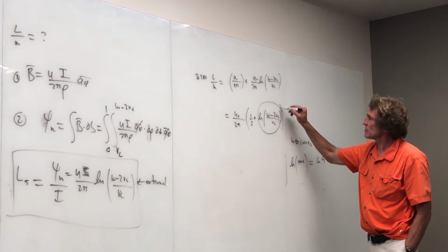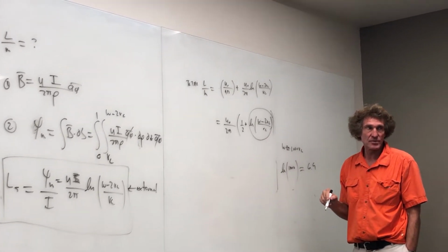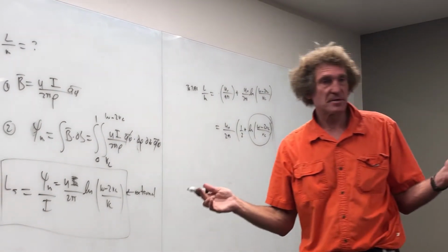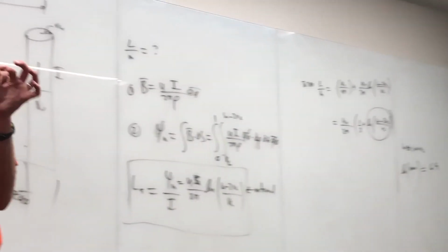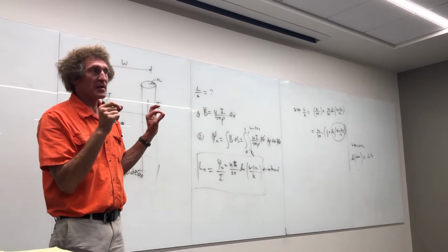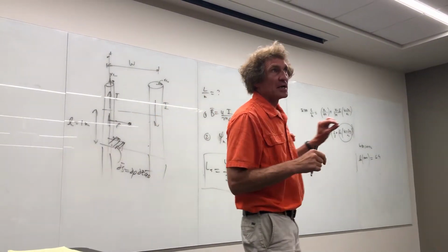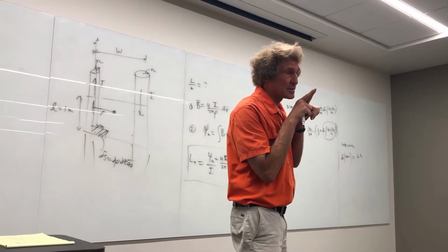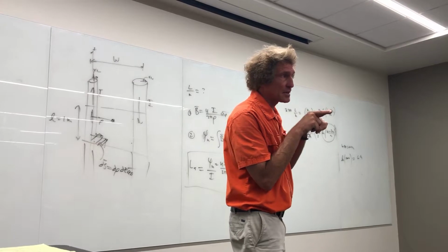My point is this. The actual external inductance is much, much greater than the internal, even for typically power lines that are separated a great distance. But if you're talking about twisted pair circuits, you know what a twisted pair is? You have wires that are twisted with each other and they have a fast twist rate, like Cat5 cable has, a lot of things. Because the separation distance is so small, they have a dielectric insulator, then all of a sudden the internal inductance takes precedence.